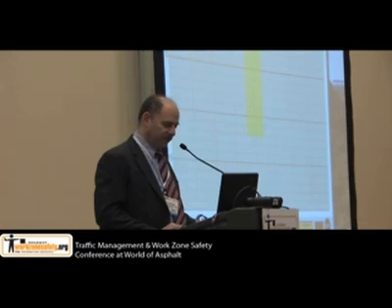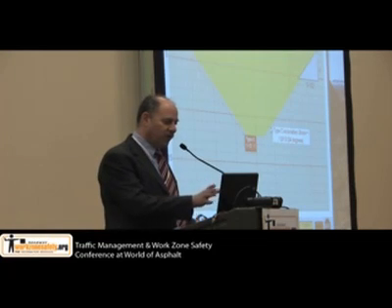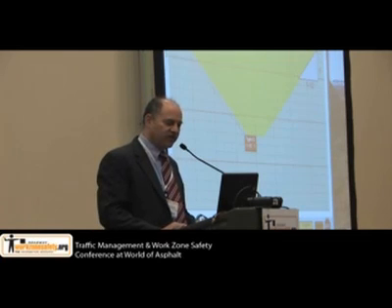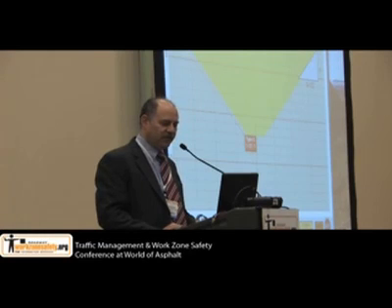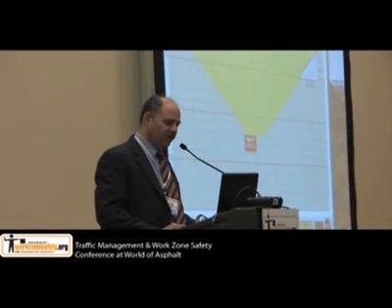Say you're going to slope it. So it's a 1 to 1.5 slope, and it shows you basically you're going to need to excavate out 20 feet in either direction. And we have the cost calculator, cost per yard of trench length. We have question marks all over this to define what these things mean, to explain to somebody what it will take to actually protect people in this system.